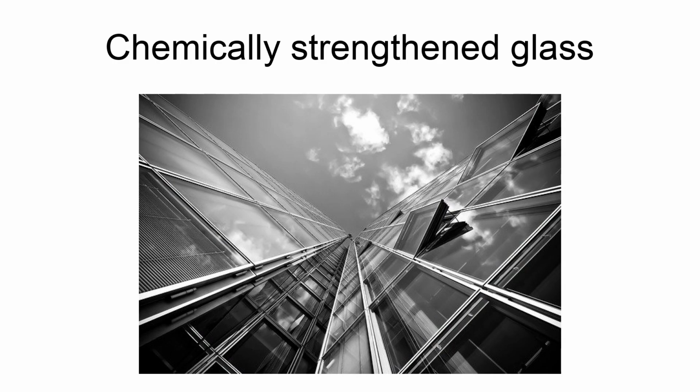Chemically strengthened glass is a type of glass that has increased strength. When broken, it still shatters in long pointed splinters similar to float, annealed glass. For this reason, it is not considered a safety glass and must be laminated if a safety glass is required. Chemically strengthened glass is typically 6 to 8 times the strength of annealed glass.